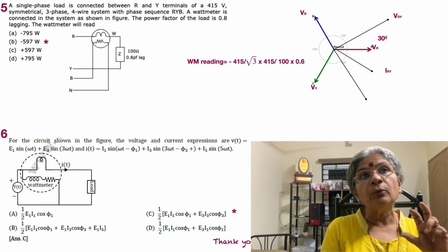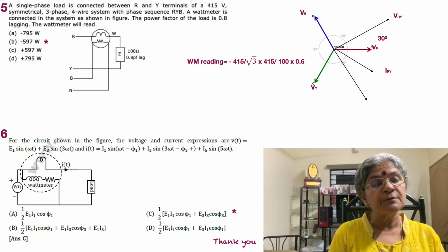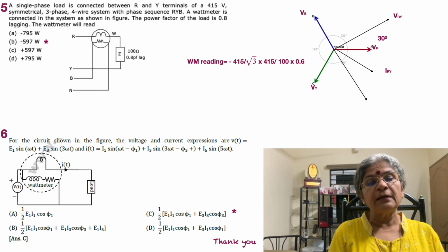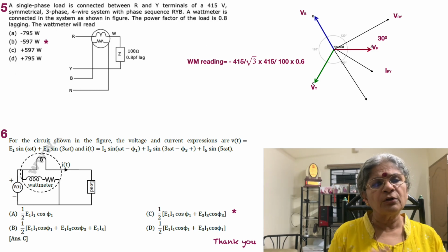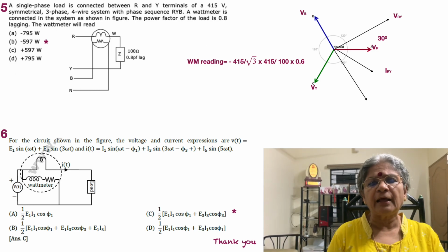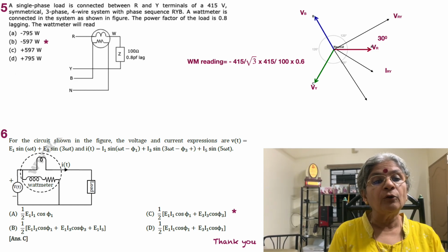The load is now connected across RY. So with respect to VRY, the power factor angle is for 0.8, and 0.8 is always indicative of 36.9. It doesn't matter, it's a smaller angle, that's all. That's also shown here, and that's with respect to VRY. Please remember that.